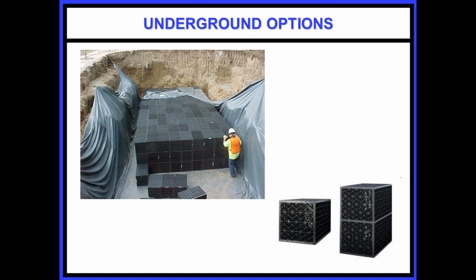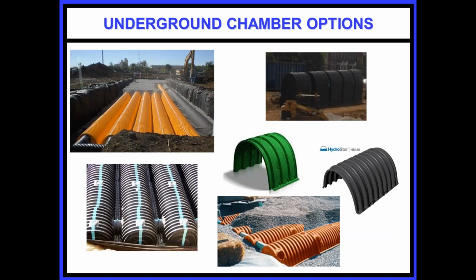They are challenged with pretreatment and how you pretreat. There's no way to maintain these types of systems without pretreatment. There's also no ASTM standards nationally for them. So it's just a matter of whether or not they can demonstrate structural loadings, because these are usually under paved surfaces. What we're going to be focusing on primarily today are chambers.